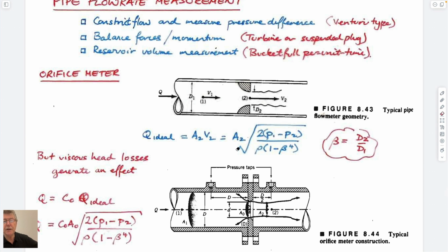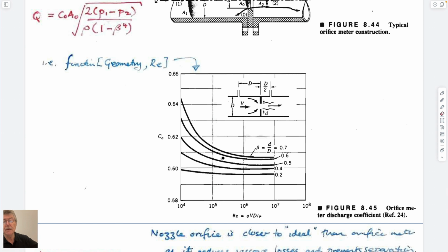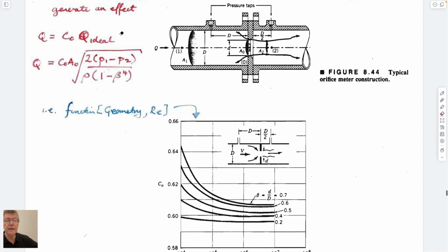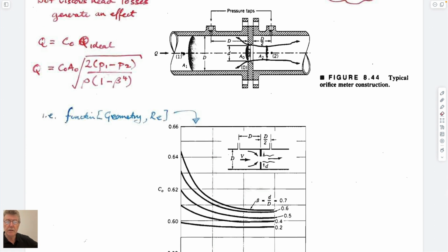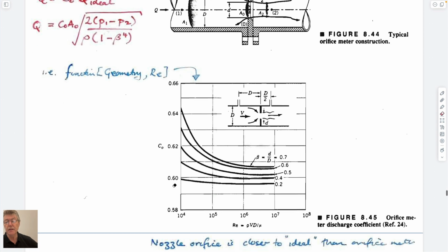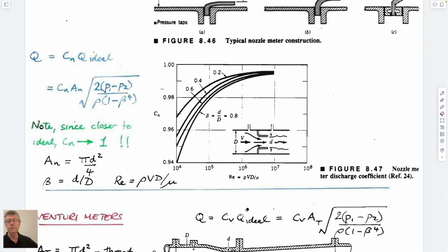We've derived this expression before, and this part only talks about what the correction factors might be for these calculations. So if you want to get flow rate as a function of pressures upstream and at the orifice, then you just correct it by some magnitude. Depending on how disruptive the plate is, the correction factor might be larger, typically a function of Reynolds number. The less disruptive the flow, the more trivial the correction factor might be, right? These are almost 1, and so it doesn't really change it very much.